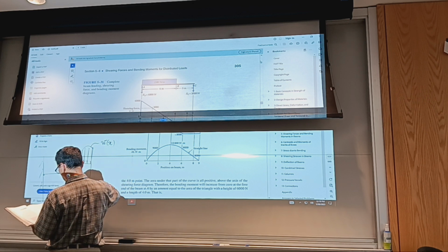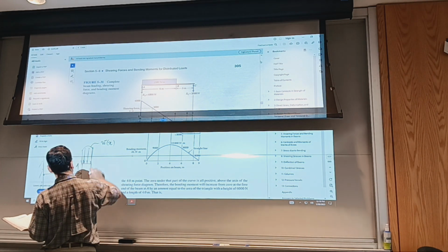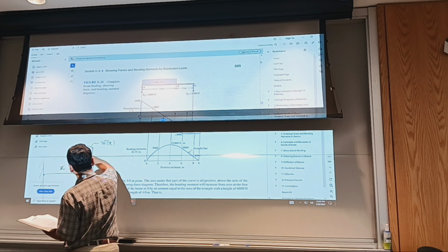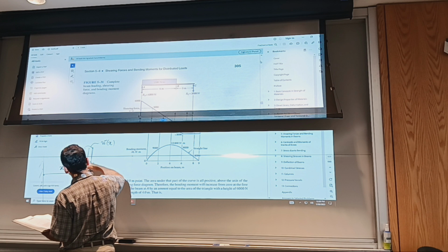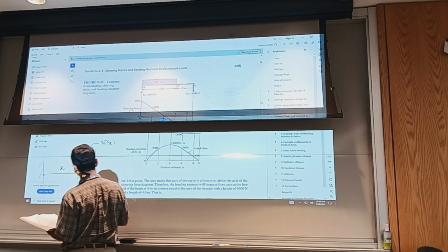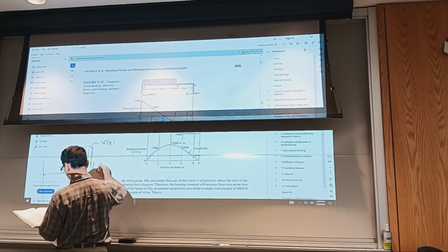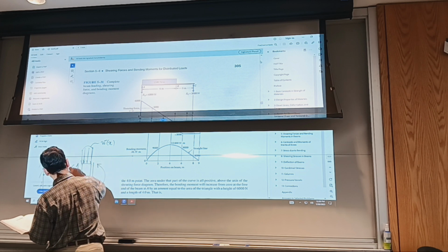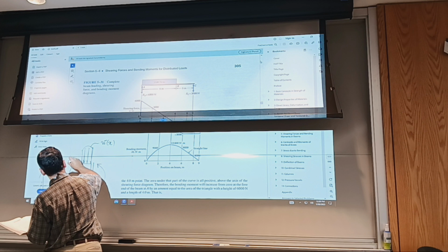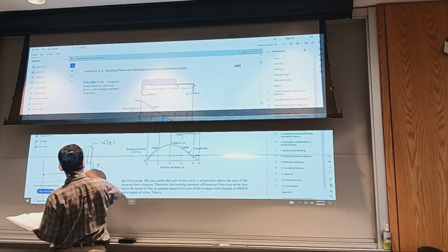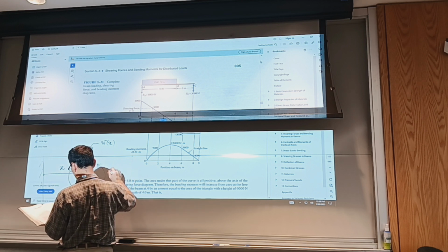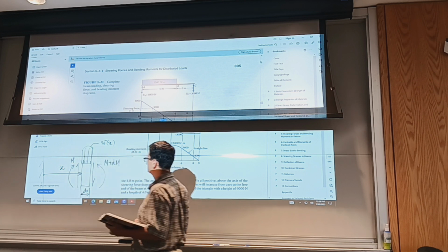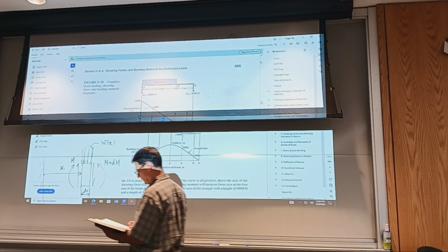And then I'll see a shear force, positive on this side, negative on this side. Of course, your shear force is internal to the beam, not on top. That's a free surface. And then we have the moments that hold us in equilibrium. Without them, you don't have equilibrium. So when it's M at location x, as I move dx to the right, I have M plus dM. So this is the equilibrium of the beam.